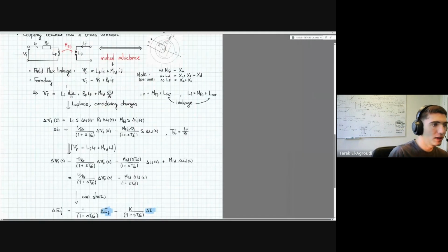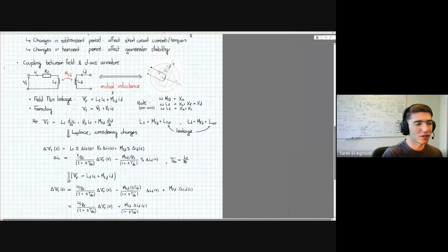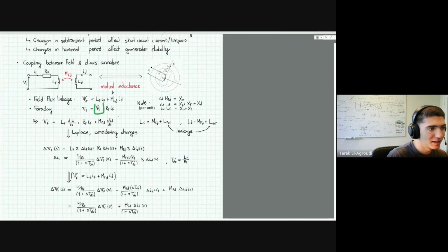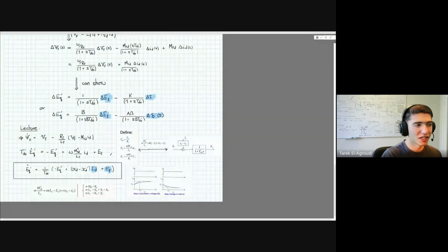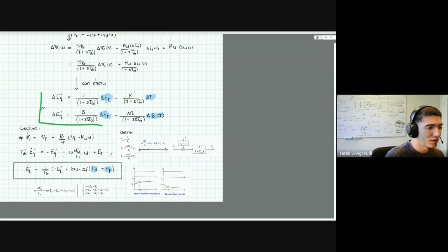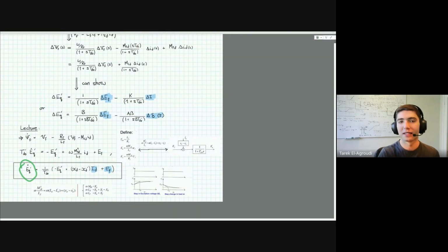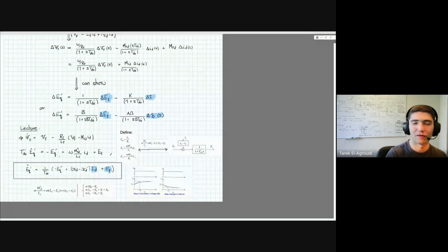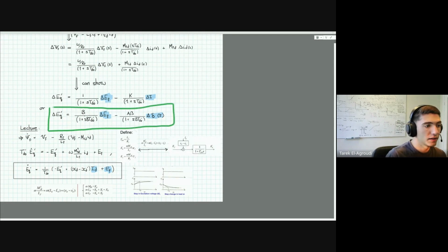When you do that, when you set up the voltage circuits and the mutual inductance and start by applying Faraday's law, after some rearranging you get a few formulas for the derivative of this transient EMF, and you can do the same for the subtransients, etc. There are multiple configurations of this, but the one that's usually used in the simplified models is this one.